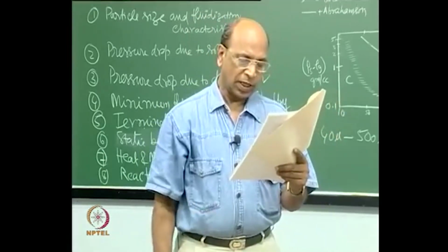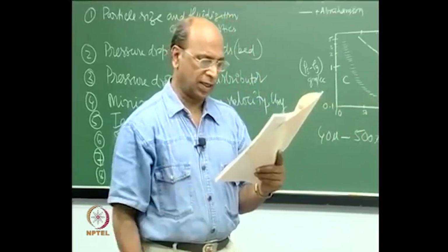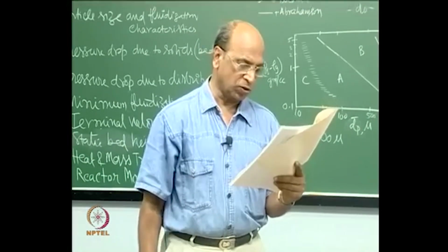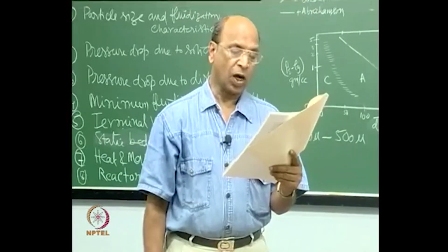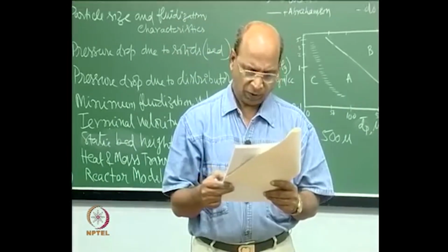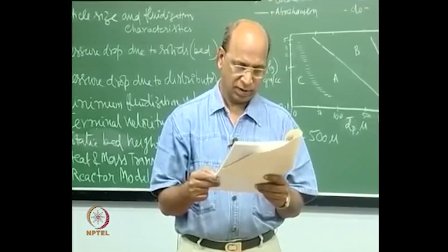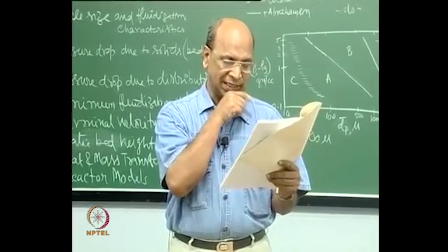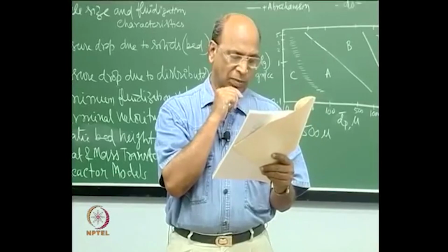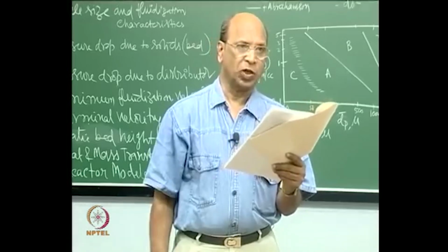They behave erratically, giving large exploding bubbles with severe channeling or spouting behavior if the gas distribution is very uneven. Drying grains and peas, roasting of coffee beans, gasifying coals and some roasting of metal ores are examples of this group.